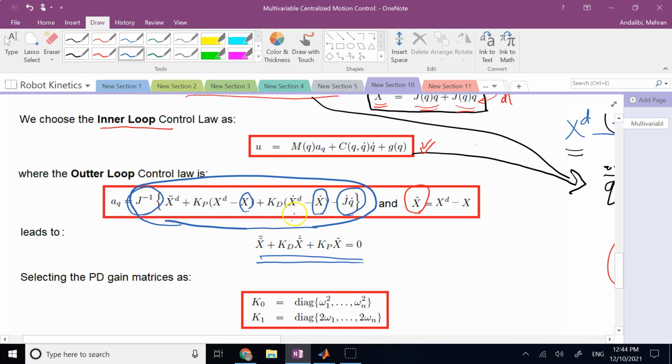And these are not always easy, because when I want Q, how do I get Q? I get it from encoders, right? When I want Q dot for a motor, I get it from the tachometers. So getting feedback for angular position and velocities is not too hard, but the question is, how would you measure the end effector position in the task space?